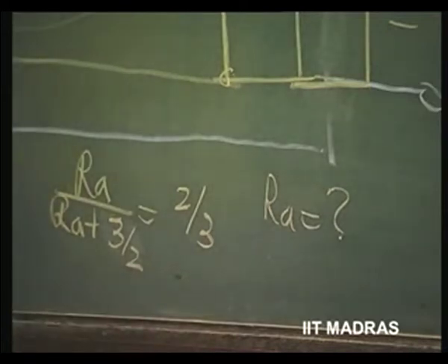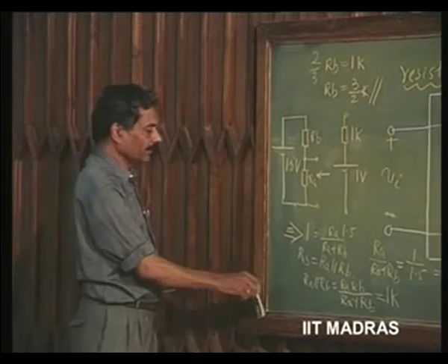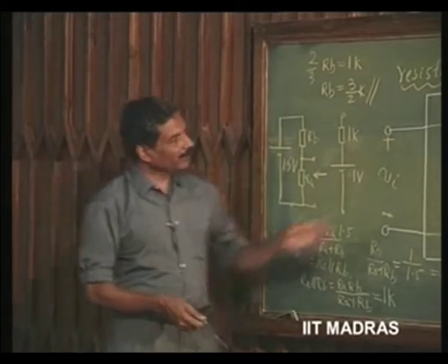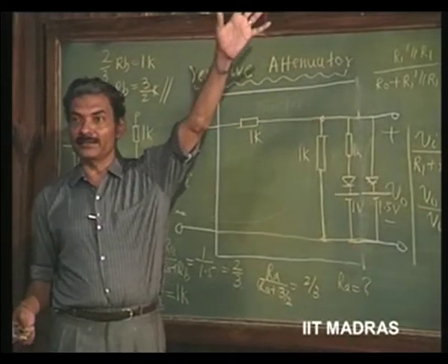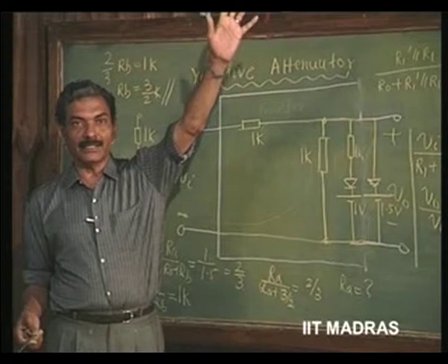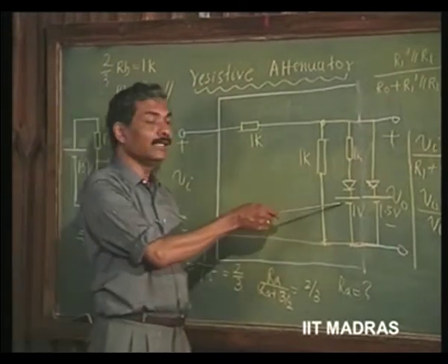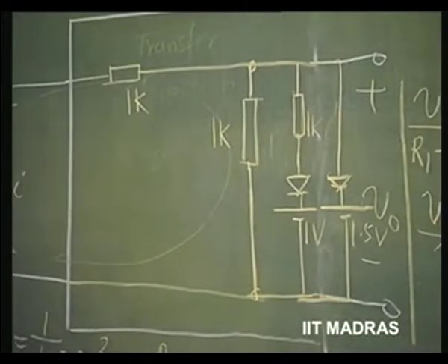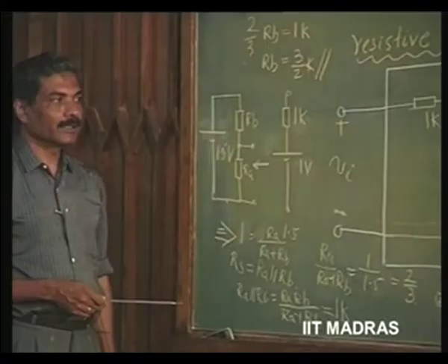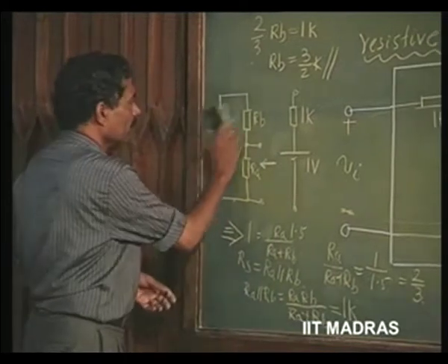So, we can solve any such problem in general by using this Thevenin's equivalent for a voltage source. Similarly, if I am using negative voltages, take the highest value of negative voltage you are likely to use. From that highest value of negative voltage, you can derive all the other negative voltages which may be necessary as voltage sources in series with resistors by using the same theorem. I would like to leave this as a problem,